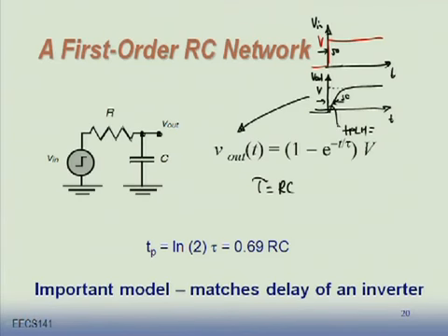Well, what is the delay until this waveform reaches 50%? Or approximately 0.7 times RC.